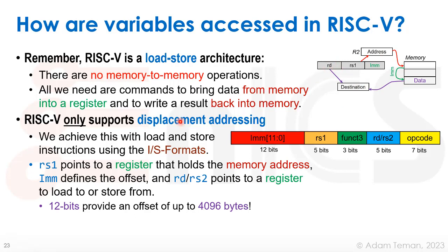And what exactly it means is that RS1 is going to point to a register, as we see that the register holds the 32-bit address that can access the entire memory. So we point to a register, and then with one level of indirection, we get the actual 32-bit address using only 5 bits that are inside the instruction itself. The immediate here shows an offset from that register.